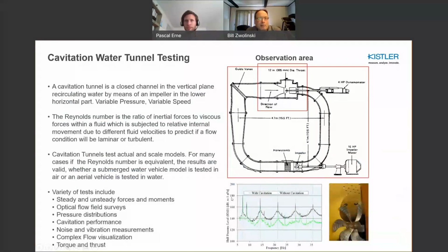As far as other pressure applications and other general applications, cavitation tunnel testing is often performed, and you can see here definitely pressure level events in the cavitation tunnel, where you can see the black curve is with cavitation, where you see elevated pressure ranges versus the without cavitation lower pressure ranges. Very common. But in these types of scenarios, what you're doing is you're able to model more with a single, say, scale model. You're able to actually test it over higher loads than what you would do in air. And that's the combination of pressure and water really allows you to do that.